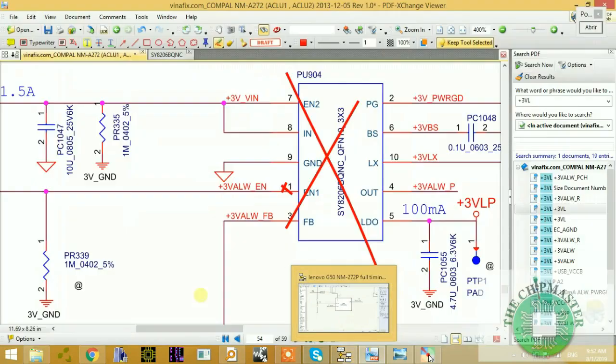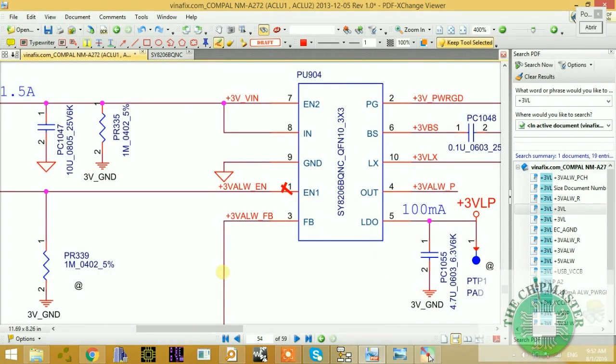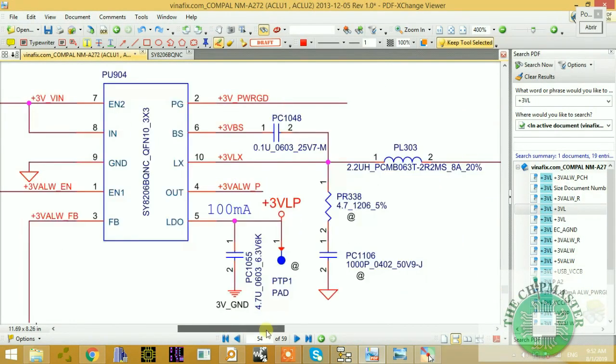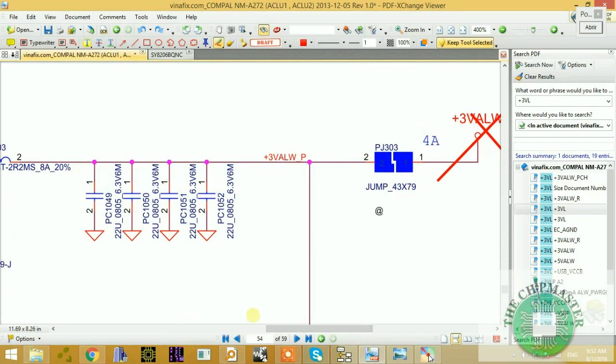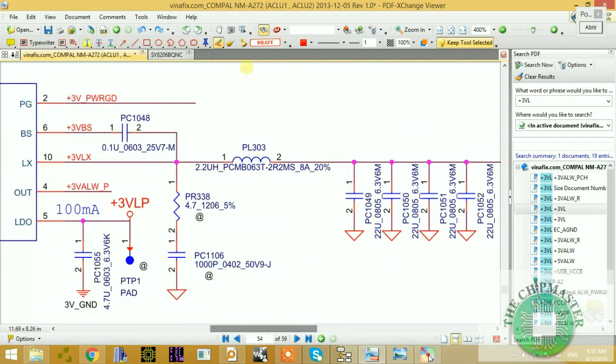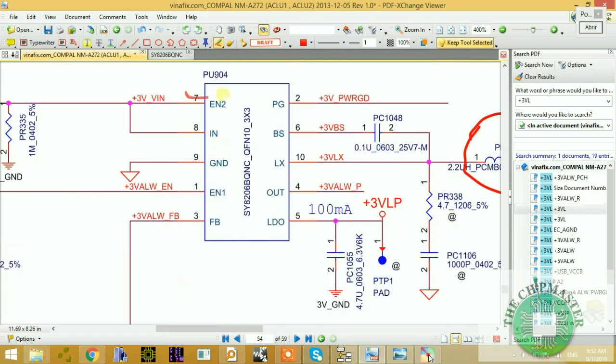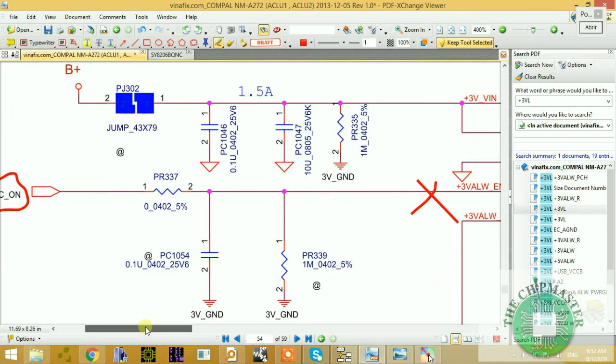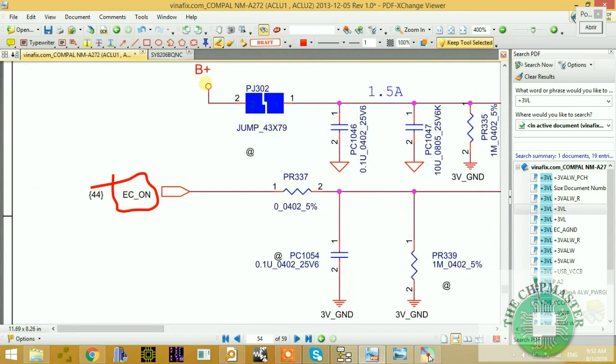So you have to pay attention. So this is the output. If you measure the voltage at this coil and you get 0 volts, and you have the 2 inputs, sorry, the supply and the low dropout, then you're missing this signal. This signal is not coming, so you should check where the signal is coming from. Alright, so let's check where it is coming from.